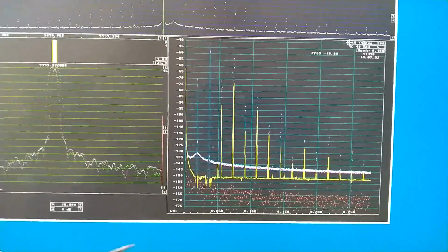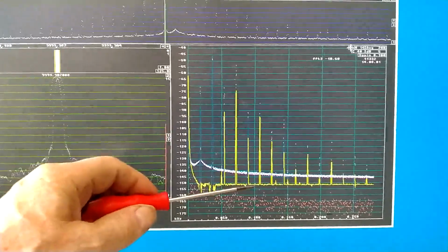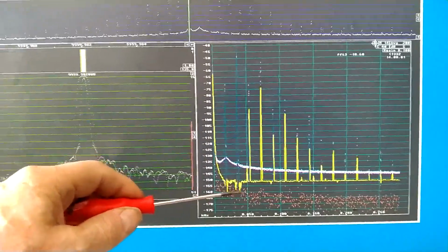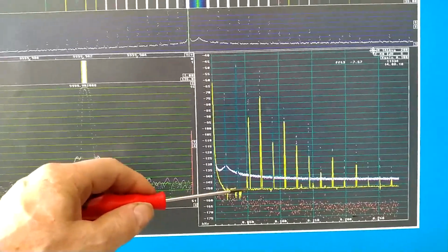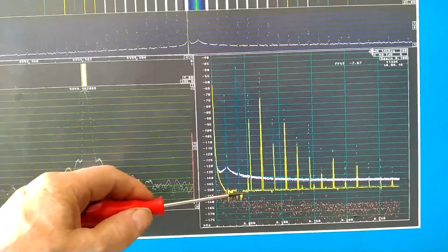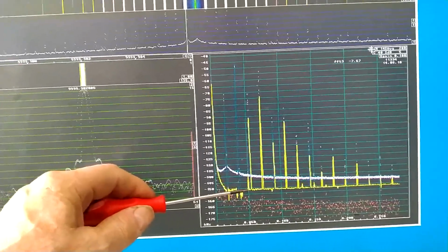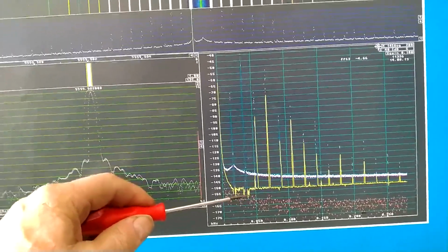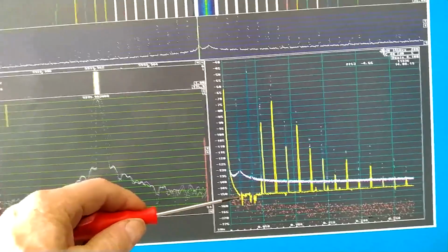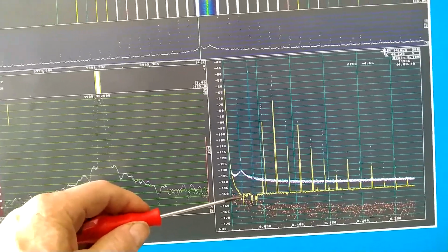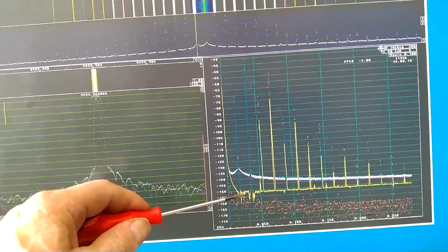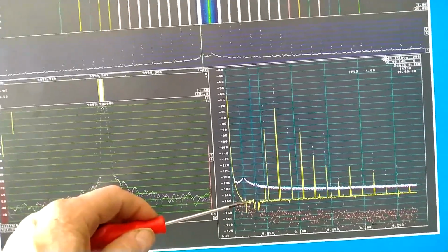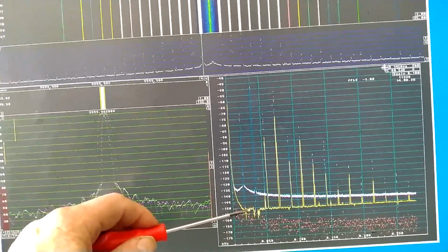With the added white noise floor at minus 151 dBc per Hertz, as I have now, I can see that I can trust this measurement only from about 50 Hertz and larger separations. And here something is unreliable. The imaginary part is equally strong as the real part. Means that the phase angle is not quite the same as before, the previous measurement.